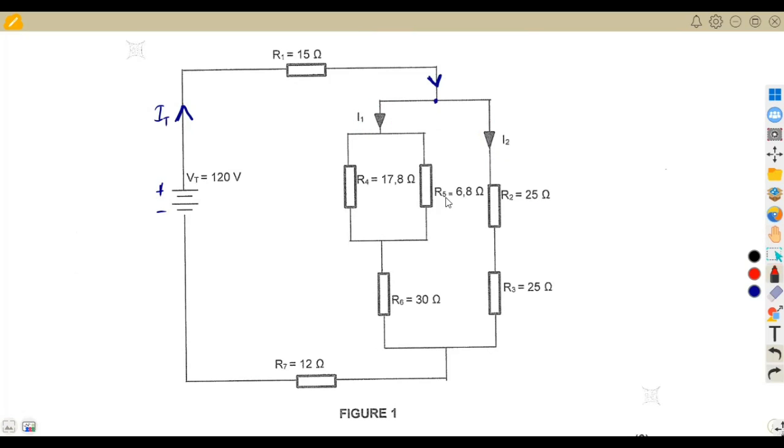These two currents flow through their resistors, and after that they enter this combination. Remember from Kirchhoff's law, these currents come back as the total current. So the current flowing here is still the same. It only changes in the parallel circuit, where one current is transferred this side and another this side. But when all these currents connect back together, they give us the same total current that we had before. So that is the idea there.